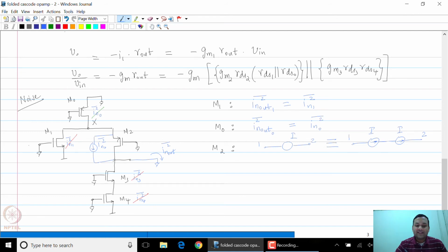And this is again not changed if I were to connect this to any convenient voltage, because there will be no current through this particular branch, and I will connect it conveniently to ground. So now how does this affect us? I can now replace this with a pair of current sources.